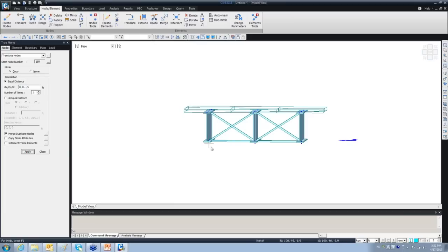So there's something here. So we can just create the bearings between these guys, and I need to make additional nodes. So I just select them, these, and go in the X direction as a positive 4, 0, and 0.